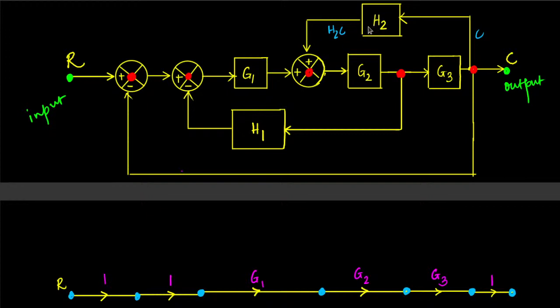So instead of having a minus sign here and a positive transfer function here, I could have a minus here, so that this signal is minus whatever that is, and I put a plus sign here. So this becomes a summing point. What is subtraction? Subtraction is nothing but addition of negative numbers. That is exactly what we have here. Is that understood?